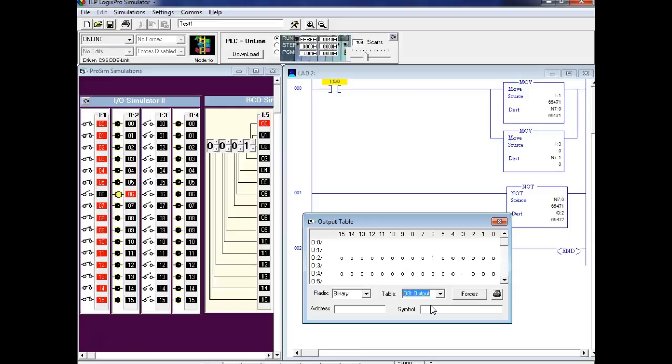From the knob. Looks like the Allen Bradley actually displays binary down here. Where Logic Pro, the guy displays what? Yeah, well, decimal. And there you can see, so this is interpreted as a negative number.